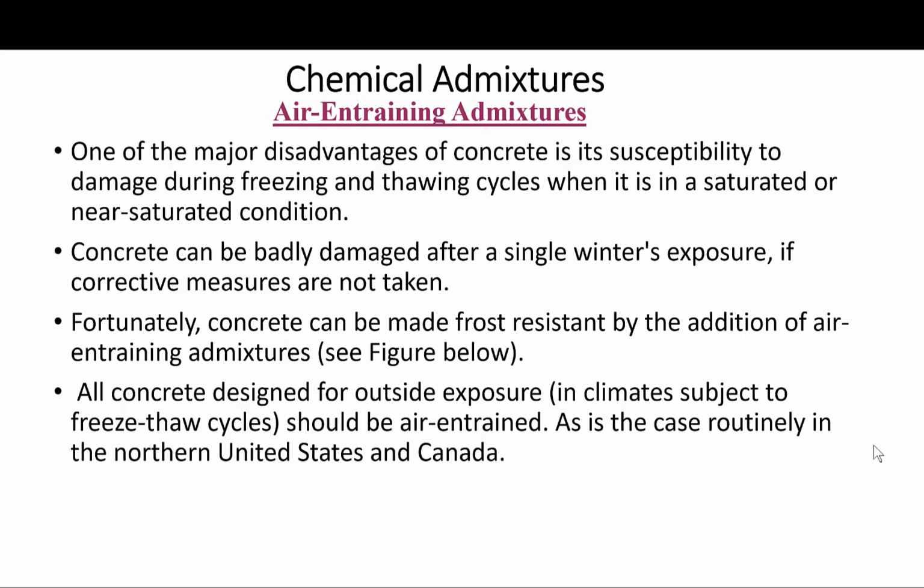One of the major disadvantages of concrete, as we mentioned before, is its susceptibility to damage during freezing and thawing cycles, when it is in a saturated or near saturated condition. Concrete can be badly damaged after a single winter's exposure if corrective measures are not taken.